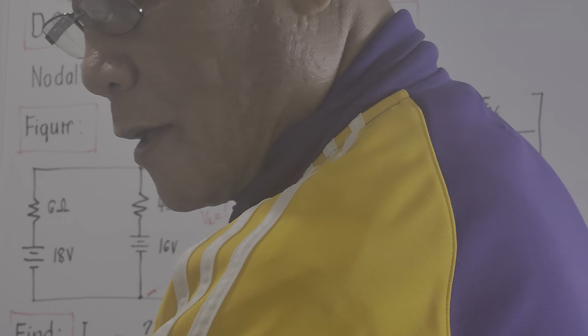Since we now have the value of the numerator and denominator separately, we could go back to this equation here. It's just a matter of substitution now. So V sub L now will be the sum of the numerators, which is 3 and 4, over the single summation of the denominator, which is 0.45833. That will be 7 over 0.45833. This is almost 1/2, so the resulting V sub L here should be almost times 2. So this is 15.27 volts. So the voltage across this will become 15.27 volts.